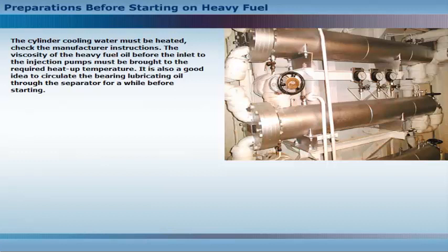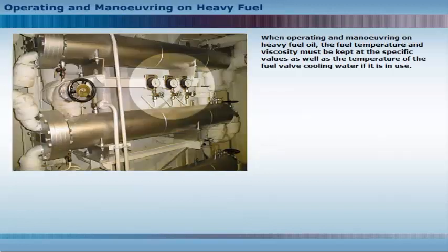Check the manufacturer instructions. The viscosity of the heavy fuel oil before the inlet to the injection pumps must be brought to the required heat-up temperature. It is also a good idea to circulate the bearing lubricating oil through the separator for a while before starting. When operating and manoeuvring on heavy fuel oil, the fuel temperature and viscosity must be kept at the specific values, as well as the temperature of the fuel valve cooling water, if it is in use.